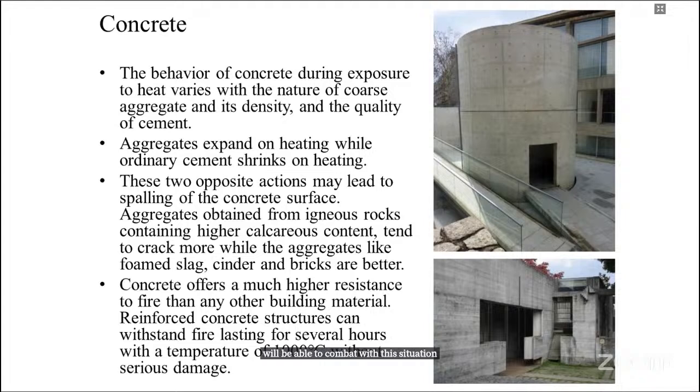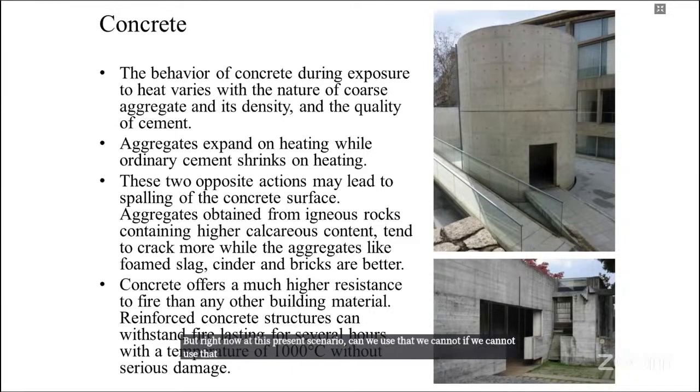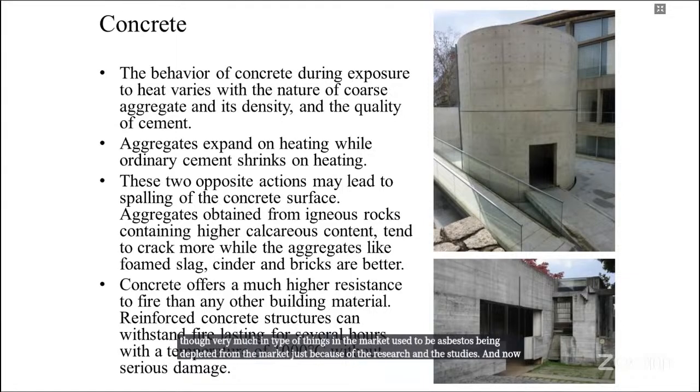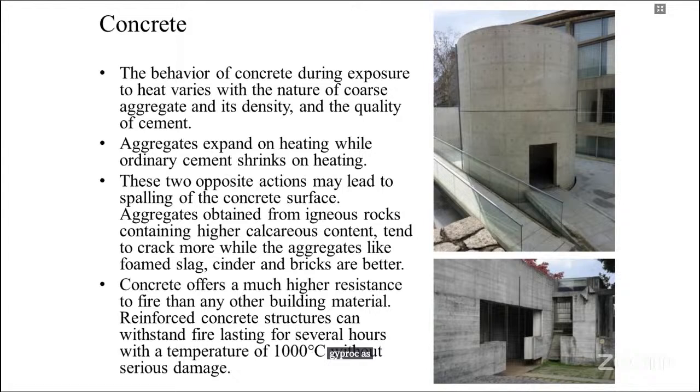So the point is, you need to understand that the combustible material can be handled with a 14 inch wall or 24 inch wall, but in the present scenario, can we use that? We cannot. If we cannot use that, then we need to go to another type of solution, which we have already discussed. Asbestos, which used to be very much used in the market, is being depleted because of research and studies, and now we are using gyprock as a basic material which is very much fire resistive in terms of its resistance and performance analysis, right?